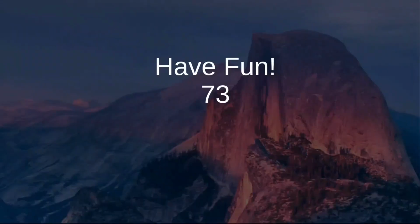Okay, everybody, that about wraps it up for this lecture. And just to review very, very quickly, we covered Ohm's law, and Ohm's law states that voltage is equal to the current multiplied by the resistance. And we also delved into the power equation, and the power equation states that the power in watts is equal to the current multiplied by the voltage. And as you remember, power is a rate of energy usage, not just energy, it's energy usage over time.